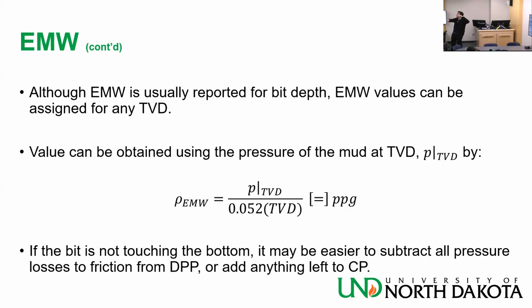Whatever depth I gained, I lost. So those 1,000 were all used to friction. Because whatever hydrostatic I gained because of depth, I lost when I was coming up, right? I went down and then up. I started from the surface, I finished on the surface. So ignore all the hydrostatic stuff, you just have the friction.